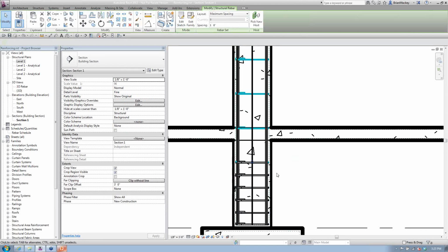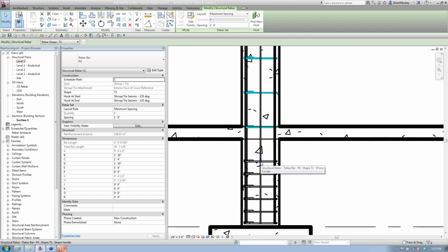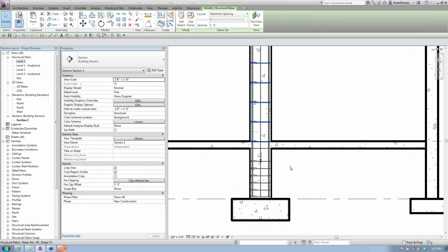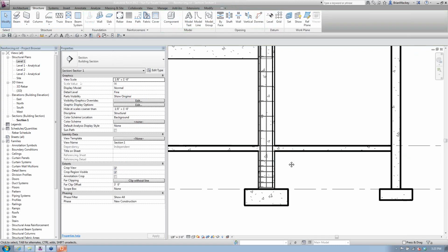Because what's really nice about this is if you select a rebar string, you can actually see that I have this little checkbox for hide the first bar, or at the top I'd have a checkbox for hide the last bar. So now I can use it to line these up so they're on top of each other and then simply uncheck that rebar so I no longer have overlapping rebar, but it's really helping me and my assistant in laying that rebar out. So I'll usually do one at the bottom, copy it up, change the value, click to the side, reselect it, stretch it where I want it to be. So it's going through, setting that all up, getting it all done.